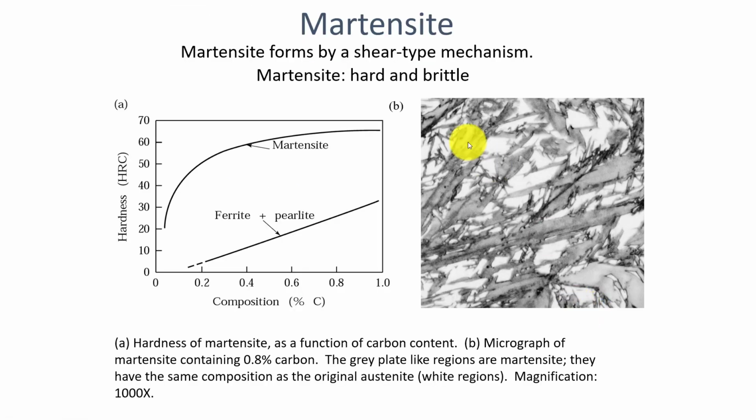Okay? And you guys remember the martensite. That's the stuff that's going to be really hard, needle, feathery, white feathery look, and we've seen some of that with the previous labs in phase in the Jomini lab, to be exact.